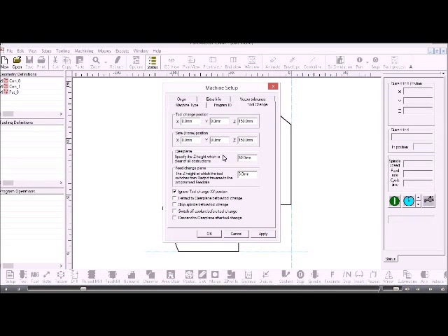The clearance plane is a Z value which should be above the work surface and above and clear of any fixturing or work holding devices. So this is where the system will rapid between XY locations between features, so this should be clear of any obstructions. The feed change plane is where the system will change, plunging down in the Z axis, changing from rapid to a feed rate before it then goes into the job and machines the particular feature.